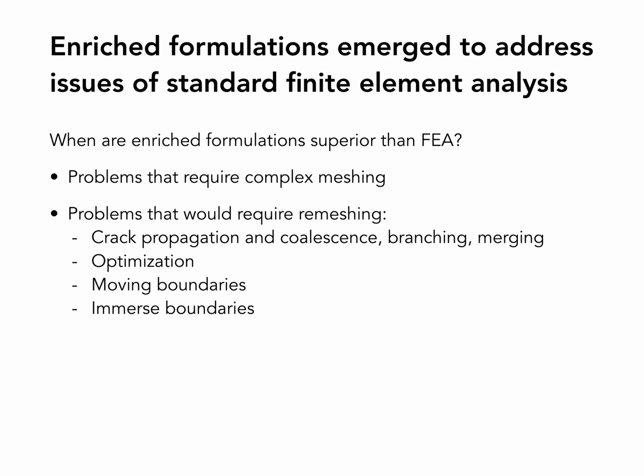Problems that require remeshing, right? Problems where you don't know the final geometry of the object, like optimization, moving boundaries, immersed boundaries, crack propagation, and so on. So these are complex problems to tackle in standard FEM. Imagine you have a crack that is propagating through a domain. Well, at every propagation of the crack front, you need to recreate the mesh, right, close to the crack front. This is very complex to do in standard FEM. So why not just use a very simple mesh and then let the formulation take care of that crack front that is evolving? So that is the idea behind this.